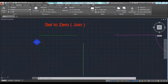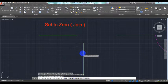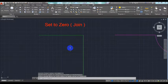Another example, when the fillet is set to 0, you can use the Fillet Command to join two lines. For example, click on Fillet Command, enter radius 0 units, select this line and select this line.